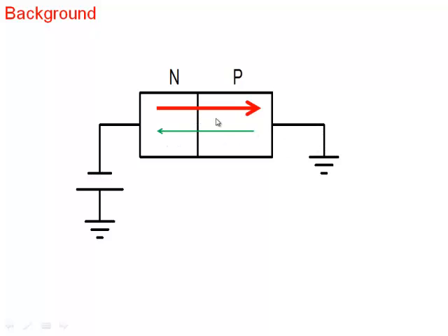So it's forward biased, and when you forward bias it, the electrons get injected from N to P region, and the holes are injected from P to N. So the total current flowing across the junction will be equal to IN, which is this one here, and IP. Note that although electrons and holes flow in the opposite direction, the current is in the same direction because they carry opposite charge. So I equals IN plus IP.